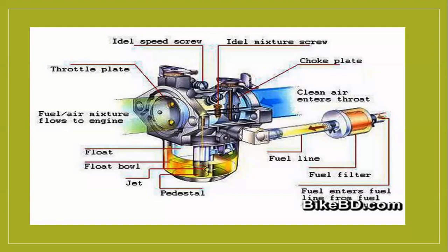So it's called a fuel-rich mixture. A lot of petrol and hydrocarbon is there, but oxygen is low. So the burning capacity is high. You give a high amount of petrol with a low amount of air, so it is easy to ignite and easy to burn. But actually, we want to conserve the fuel, so we will open the choke valve.